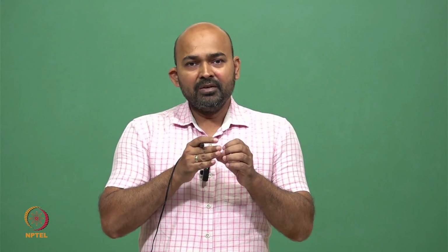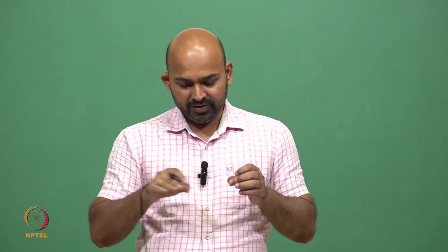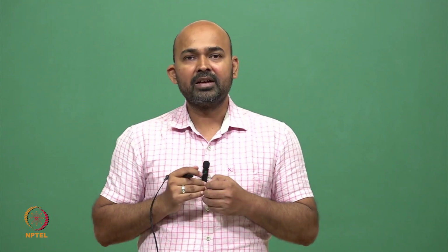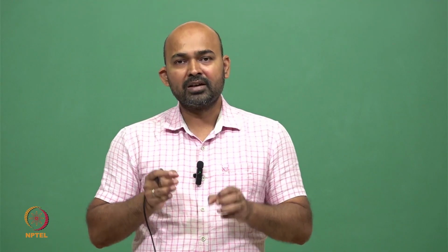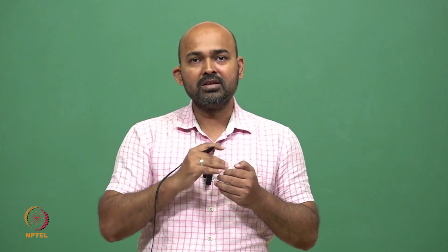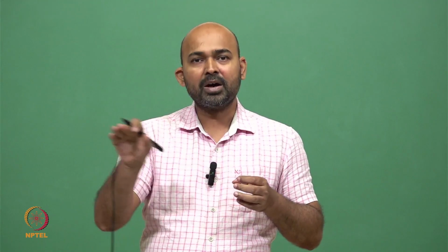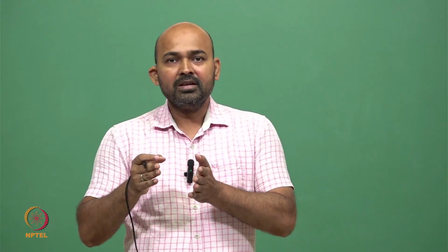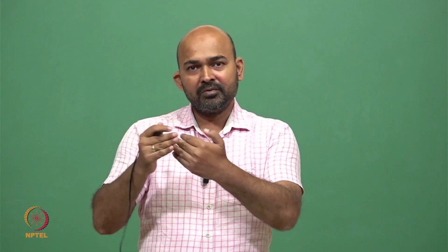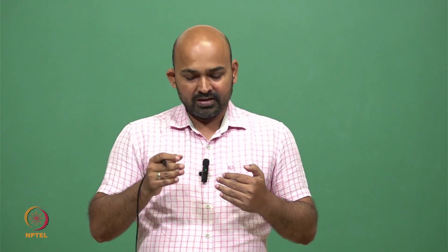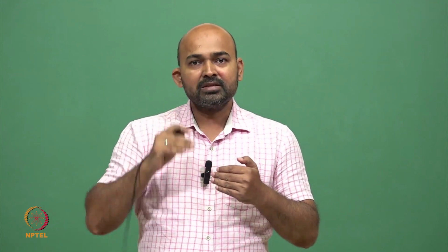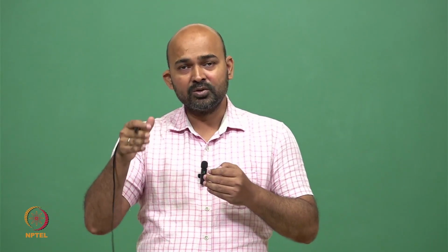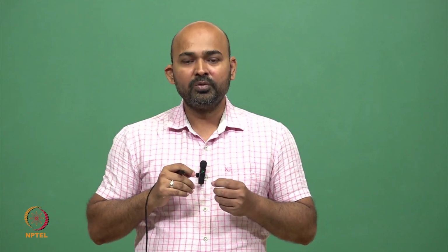Now this electrical wave will travel as an acoustic wave in the SAW device. Based on the number of reflectors, there will be a reflected wave. So if we have one reflector, it means it will be reflected there once. Some part will be reflected, some part will be refracted in the same direction. Then we have three reflectors, it means it will be reflected at three instances. So it will generate three peaks in the reflected signal, and further we have two reflectors. Those two reflectors will give rise to two peaks.